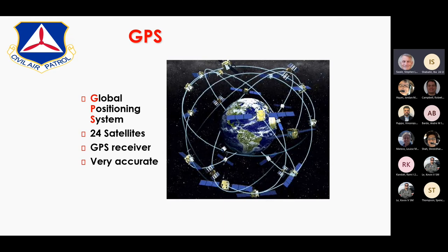For MOs and also pilots, recall for G1000 airplanes that you need to go to the aux page, and simply by looking at the GPS, what GPS satellites are being received, if they have a little W sign on them, you'll know that they are receiving WAAS. And if they're not receiving WAAS, then the rules for approaches that require WAAS do not apply. What does apply is something known as RAIM, which is Receiver Autonomous Integrity Monitoring, and there are rules that the pilots that are IFR qualified should know about on what you need to do there.